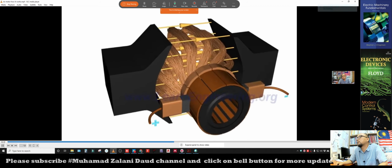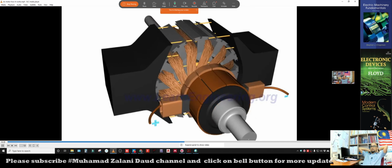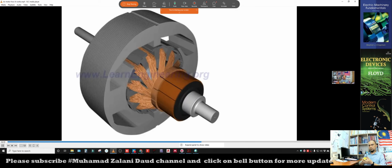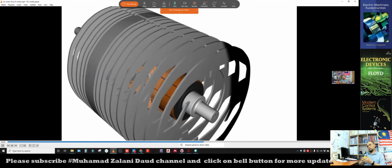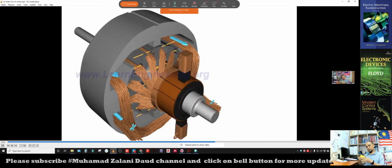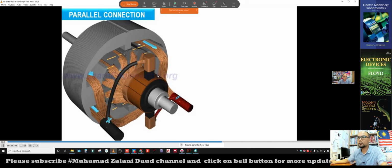In a practical motor, the armature loops are fitted inside slots of highly permeable steel layers. This will enhance magnetic flux interaction. Spring-loaded commutator brushes help to maintain contact with the power source. A permanent magnet stator pole is used only for very small DC motors. Most often, an electromagnet is used. The field coil of the electromagnet is powered from the same DC source. The field coils can be connected to the rotor windings in two different ways: parallel or series.